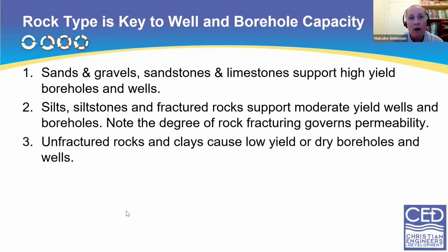So there's a further comment on the unfractured rocks. The other rock type we avoid is clays because they are pretty impermeable. They're not impermeable, they're just much lower permeability and unsuitable even for low yield wells. However, clays themselves also often contain layers within them that are good producers. So an example would be the Weald clay in southern England, which has the Tunbridge Wells sandstone in it, which is locally a very important water supply. But if you look on the map, it just says Weald clay. Certainly if it's a regional map.